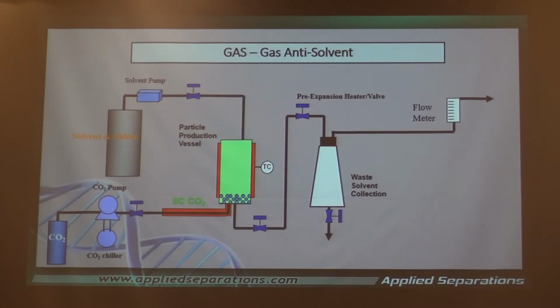Now, we can change the solvating power of the CO2 based upon the pressure that we put in there. So, this is a very powerful tool that you can dissolve the solvent in the amount that you want, and the rate that you do that will determine the size of the particle. So, faster, just like any kind of precipitation, if the precipitation occurs quickly, then the particles will be smaller. And it's the same situation that you have here. But now you have a means of controlling this by controlling the pressure, the solvating power.